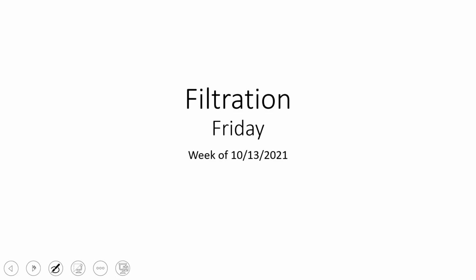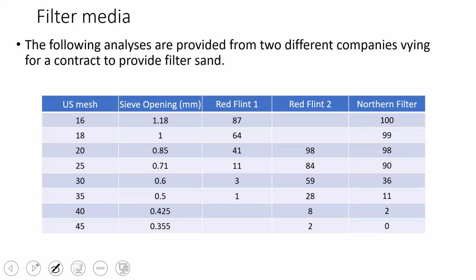Today's lecture focuses on filtration design. We'll focus today on the hydraulics of filtration, talking about, in this case, granular media filtration. So we're talking about passing water that's been treated, typically through some sort of screening followed by treatment, either softening or coagulation and sedimentation, and now we're looking at removing those particles that were too small to be removed by sedimentation.